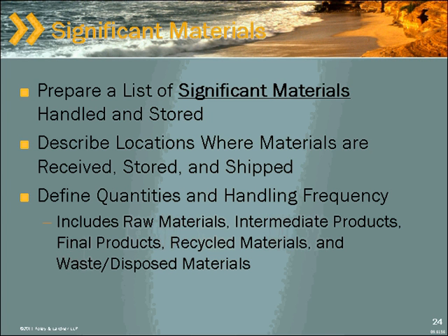An interesting way to identify what was intended by this list is to go to the 11 questions in the non-exposure certification. Right, and the EPA one. That's also on the State Board website, but when you look at it, it clearly identifies what you can't do and still comply with non-exposure. I believe that the converse of that is these are all the things that, if you do any of them, have to be considered as a significant material.